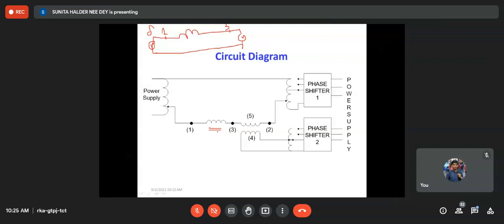When we write anything in programming, then we make that a computer simulation. So is it justified to represent a line by an inductor, because actually a line has distributed parameters? But when we consider a lossless transmission line, even if it has distributed parameters, we can simply represent it by its inductance only. With that logic, we represent the line in this way.